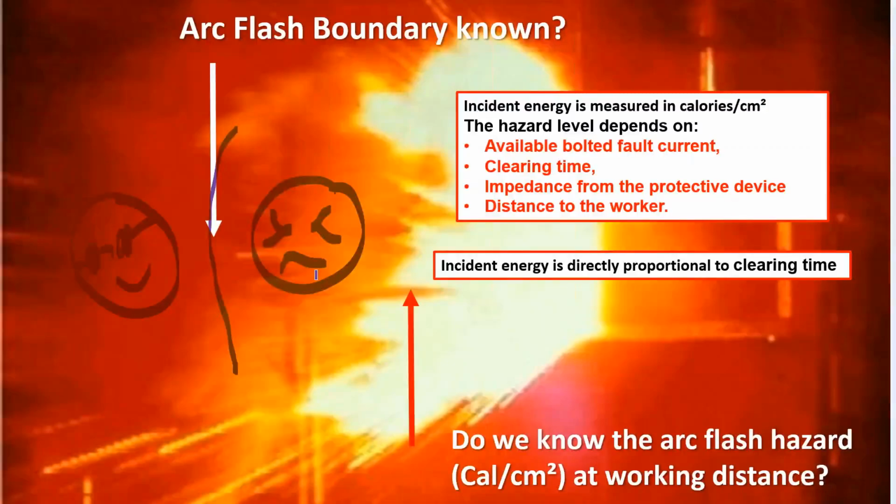There really isn't a whole lot of protection, because you feed it through the impedance of the transformer, and then you go up to the fuse feeding the transformer, and that may blow quickly if you have a fault on the conductors going to the transformer from the utility. So it gives protection for that, but it doesn't give you a lot of protection downstream from that. So the arc flash level is going to be very high, and because of the time element, it's going to take a lot of time to read through that impedance.